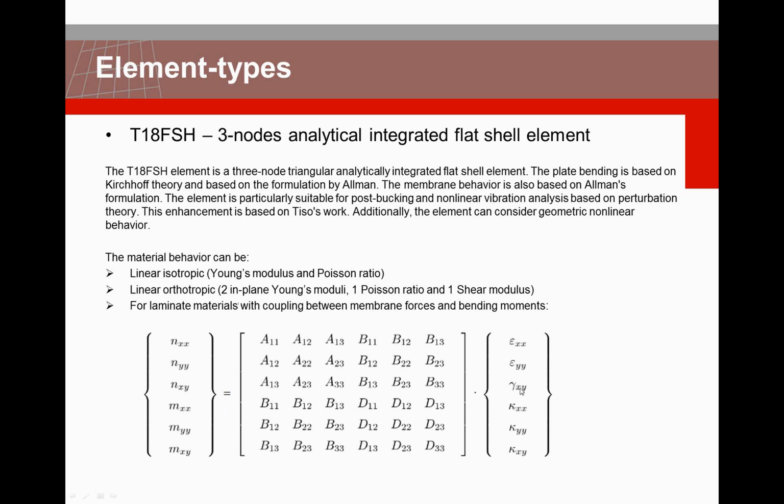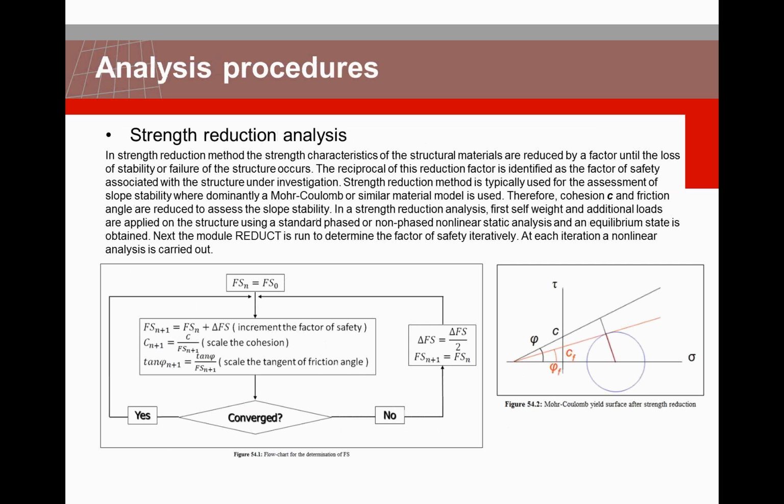in-plane strains, curvatures, and cross-section forces and bending moments. And this model can be used with the standard linear isotropic material definition or with linear orthotropic material definition, but it also offers possibilities for laminates, which gives different material properties defined in different layers.